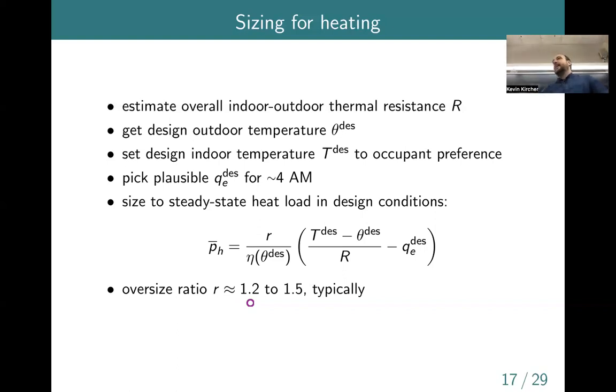And after that transaction, they don't really want to hear from you. But if you're unhappy with what they put in, oh, it's not keeping my house warm, then you'll call them back. And those callbacks are basically terrible in the HVAC installer industry, I guess. They hate them. So to avoid callbacks, they say, we're going to put something in that's big, so you're not going to get cold, essentially.